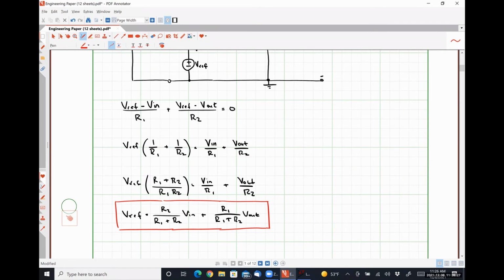So what this tells us is that, effectively, we're going to solve for the input value that causes our output to either swing high from a low state or the input value that causes the output to swing low from a high state. These are what are called our upper trigger limit and our lower trigger limit.